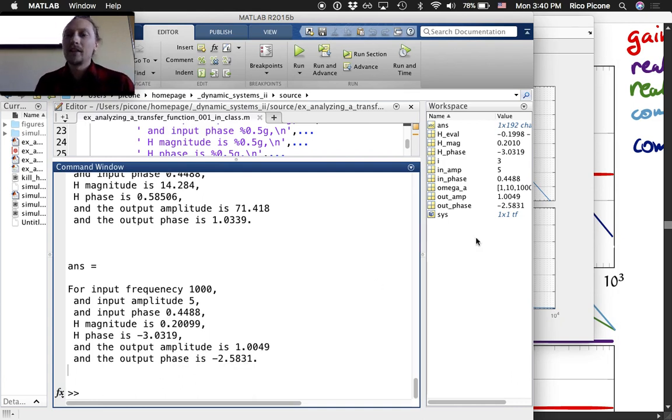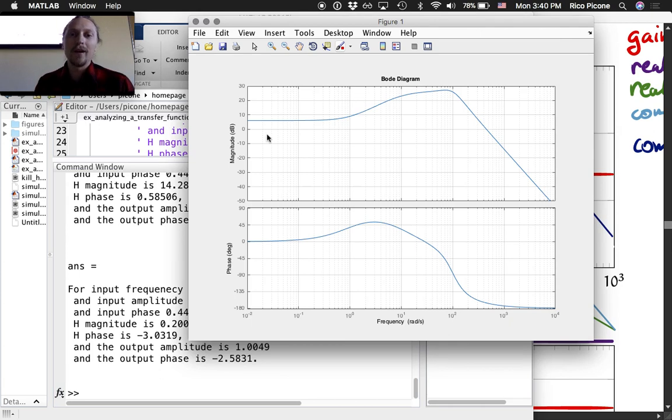We kind of see that there's this frequency response, right? So if you put in a sinusoid down here, we're doing one thing to it. The output amplitude is coming out to be a little bit more than the input amplitude. Out here, output amplitude is coming out to be a lot higher. So if you're in some intermediate range in your input frequencies, you're going to see this big amplification. But when you get to higher frequencies, you're going to see this attenuation of your input.